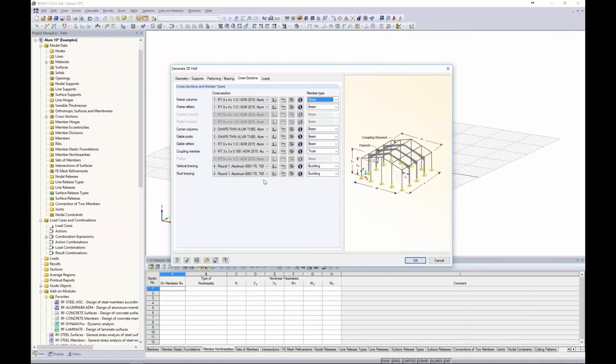The vertical bracing and roof bracing, it might be quite common to set this as tension only, which is fine. I more so recommend that for something that's a cable or a rope or wire that truly doesn't have any compression capabilities at all. But for us today, since we're using a rod, it has a small amount of compression stability. So what we could set this to then is buckling. And what buckling will do is take the member out of the analysis if it exceeds the Euler buckling limit. So I suggest to do that over tension when you have a rod type member.